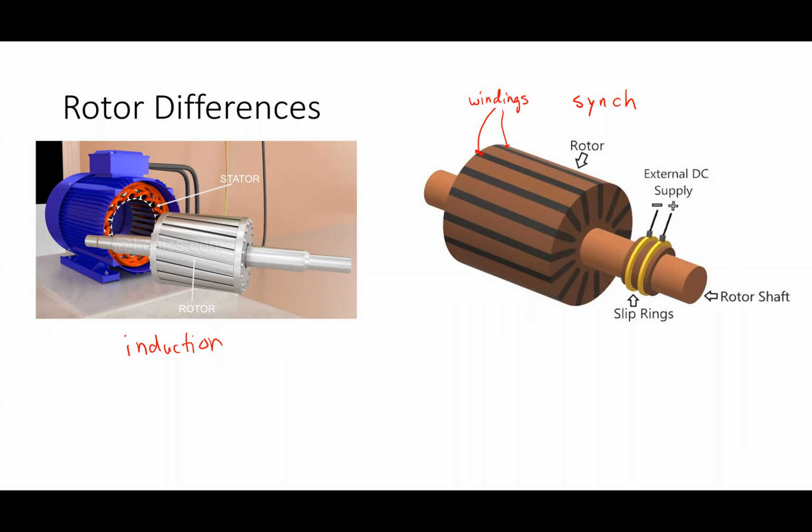So there's windings all along that thing. Wherever I see a slot like this, there's a winding. And I get current into those things by applying a DC voltage supply to what I call a slip ring. There's a set of brushes that touch these pieces of carbon right here, and a current would flow in, enter these windings, and then flow back out. And this is that field current, I sub F. That's how that guy works. So there is a direct connection to that thing.